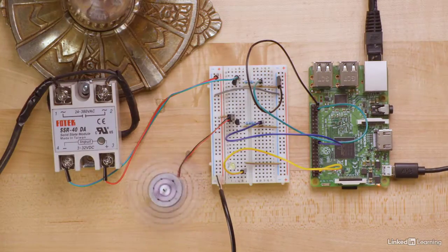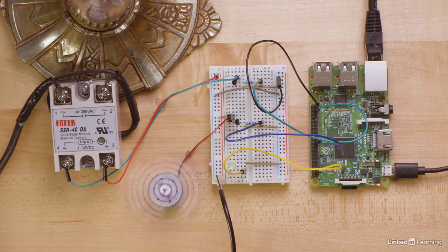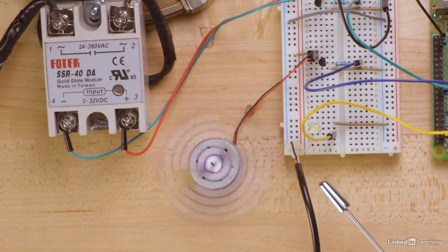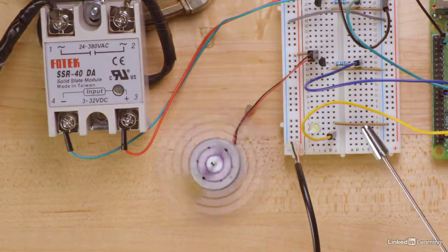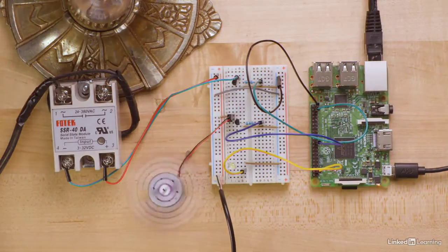The base of the transistor is connected to the Raspberry Pi, and this is what turns on and off the signal. Think of the base of a transistor as a switch that allows current to flow from emitter to collector. The motor, also known as the load, is connected between 5 volts and the transistor collector. With a transistor, we can safely control a small motor.